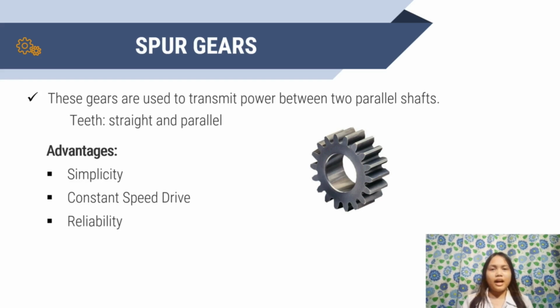Reliability. Unlike other power and motion transmission components, spur gears are unlikely to slip during operations. Cost effectiveness. The simplicity of their design also allows for greater manufacturability, making them less expensive to fabricate and purchase even with high specific or customized dimensions. Efficiency. Spur systems have power transmission efficiencies between 95 and 99% and can transfer large amounts of power across multiple gears with minimal power loss.